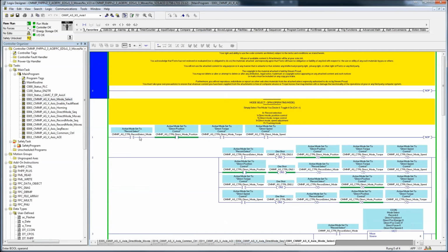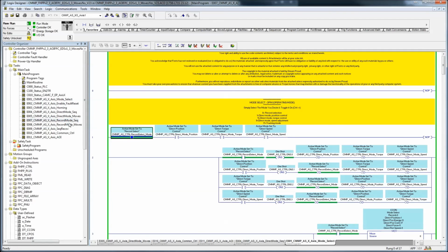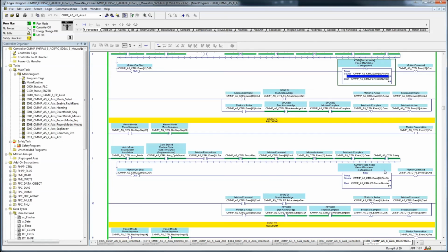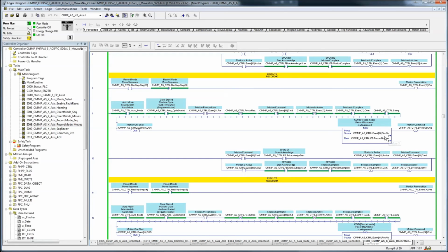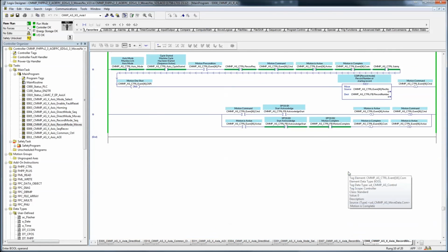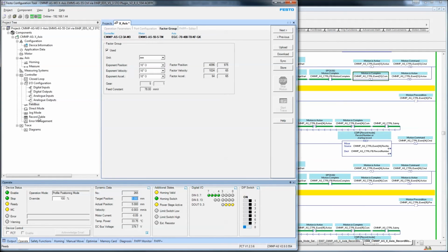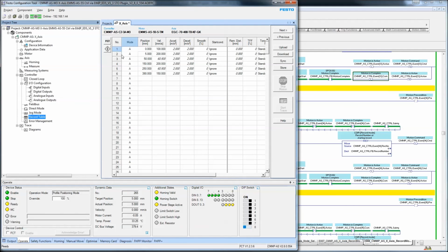same thing goes for record mode. So Control T, get into the record mode, and go to the record sequence and moves. Same idea, except all we're doing is shoving a value, which is our record number, into the controller, and same events, meaning you will eventually turn on start task and get an acknowledge. Now you're active. Once you're active, you're waiting for the acknowledge start to go off and the motion complete to come on. You get a motion complete. Very simple, straightforward. You, of course, need to have programmed the record table with 6 moves, which I have.